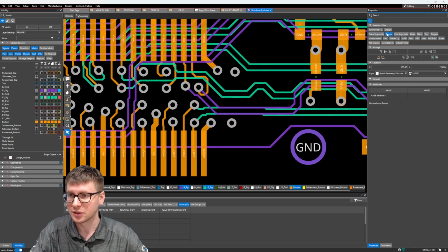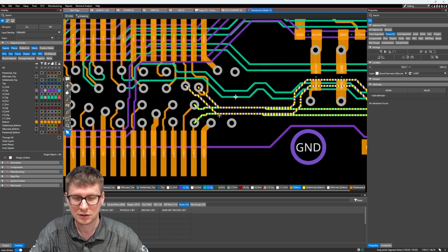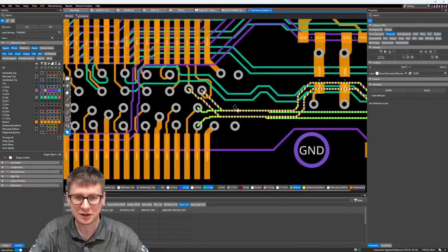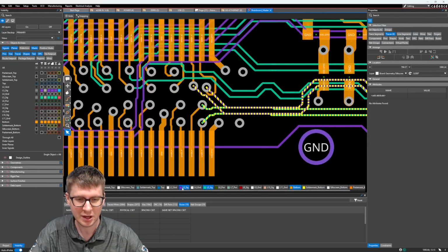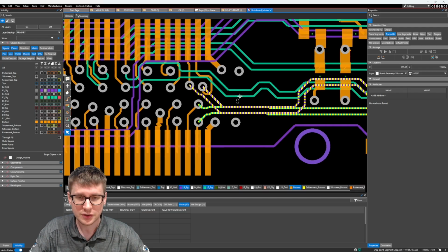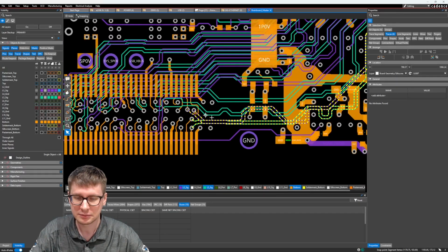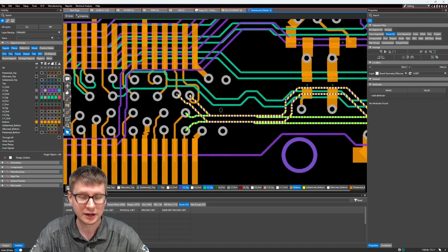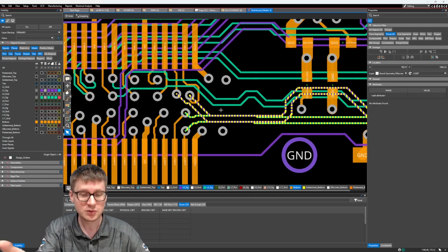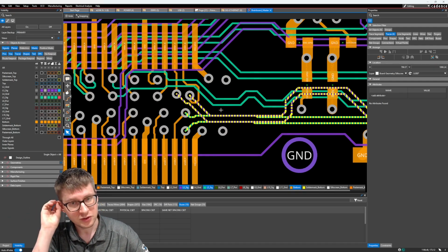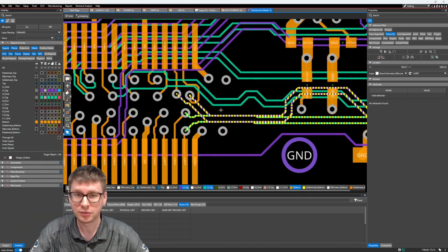In order to get started, first thing you need to do is actually select a couple traces. So I will select these 4 traces right here. Now the reason I'm selecting these traces specifically is you'll notice that I have them on the layer 3 signal and layer 5 signal, so 2 different layers. And also, they are in what I would call kind of a multi-layer setup where, on this board, we chose layers 3 and 5. Maybe on a different board, someone might want to route these on a different layer for whatever reason.